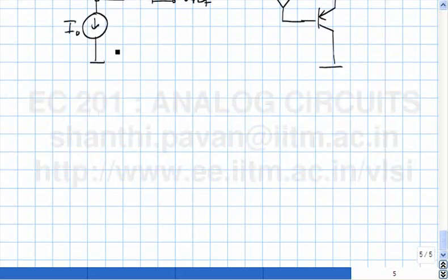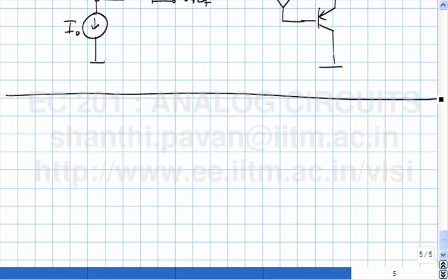Great. After stabilizing the bias, we again realize that whether it's a PNP transistor or an NPN transistor, the incremental equivalent has to be the same, and in principle they are all equivalent to an infinitely large voltage controlled current source. If you just use this, the gain is poorly controlled and so on. So you can put this as the forward amplifier in a feedback loop and make all the four basic types of controlled sources where the control parameters are all independent of the device parameters itself.